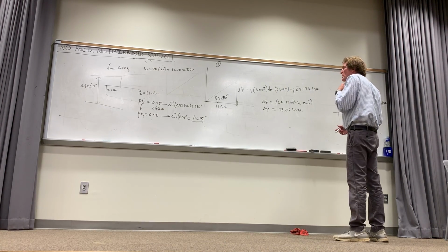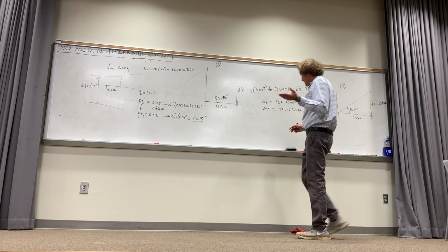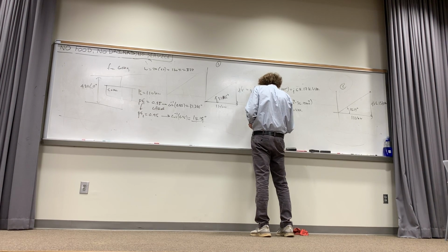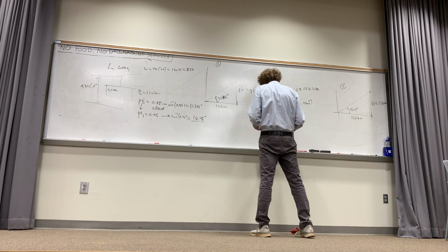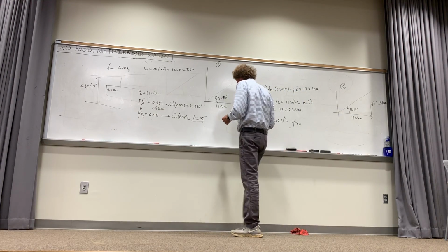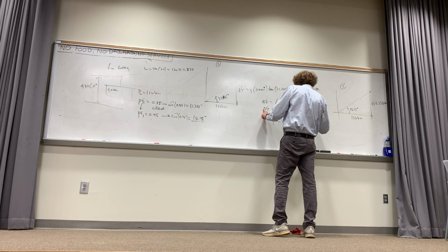All right, now, how do we get the value of the capacitor we need? We do this. We know that Q, the reactive power of the capacitor, would be minus j omega C times V RMS squared. That's minus jQ of the capacitor.